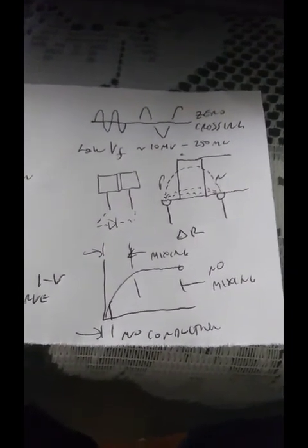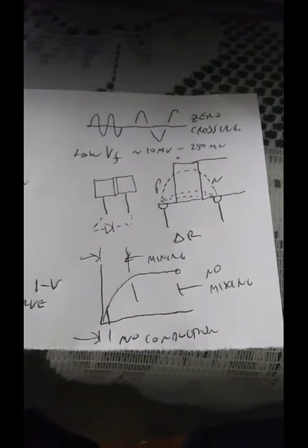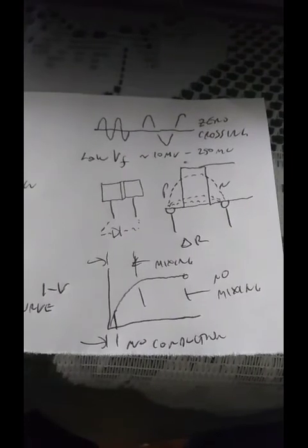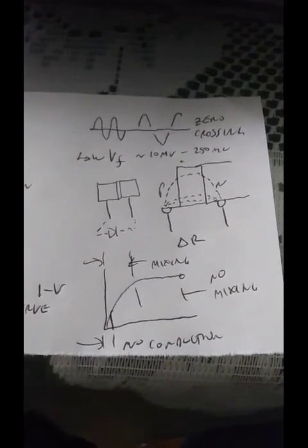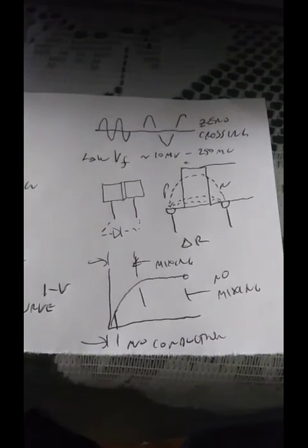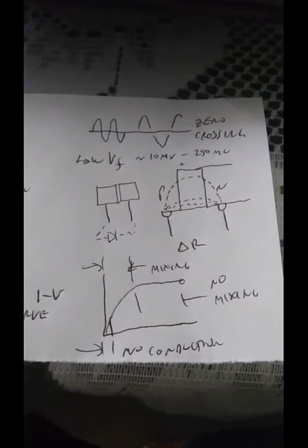It should be fairly obvious that the diodes must be very carefully matched. And I'll show you here in a second a data sheet from Infineon for one of their diodes that lists matching somewhere between 10 and 20 millivolts, which is very, very good. I've measured far more than that difference in these original diodes in a Drake with a diode test. And I'm going to stop this video here at video 2, and video 3, balanced modulators and mixing, will be showing the diode characteristics and onward. KBYP.